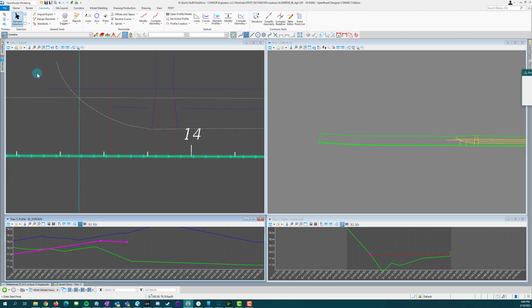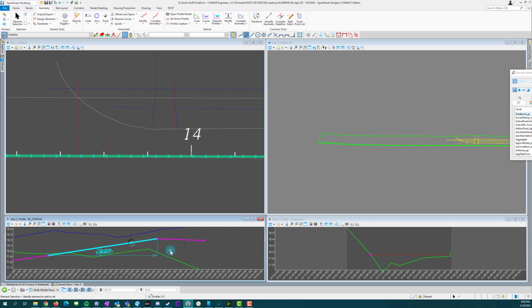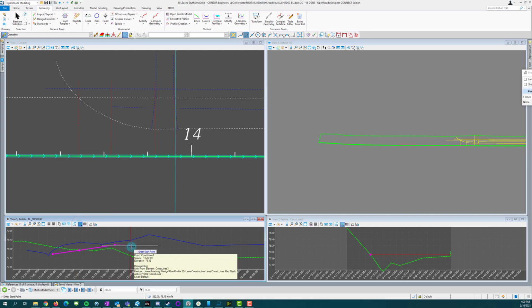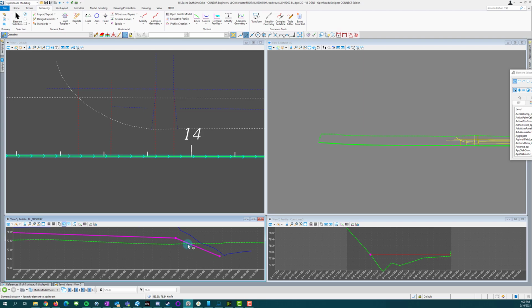So you can see I don't have a crazy break over here. 1.4 to 0.3. This is another thing that's up to interpretation as well. I've gotten a little crazy in some of my jobs where maybe I offset this another 10 to 15 feet and put a point out here and then make a vertical curve so I have a smoother transition into this driveway and then coming out and back down. But we won't need it here because it's going to be pretty smooth as we come out of here through here and then down. And like I mentioned before, this one is a prime example where you might want to push this point back a little bit more, maybe make a little bit of a landing down here to make this smoother as you go towards the street.